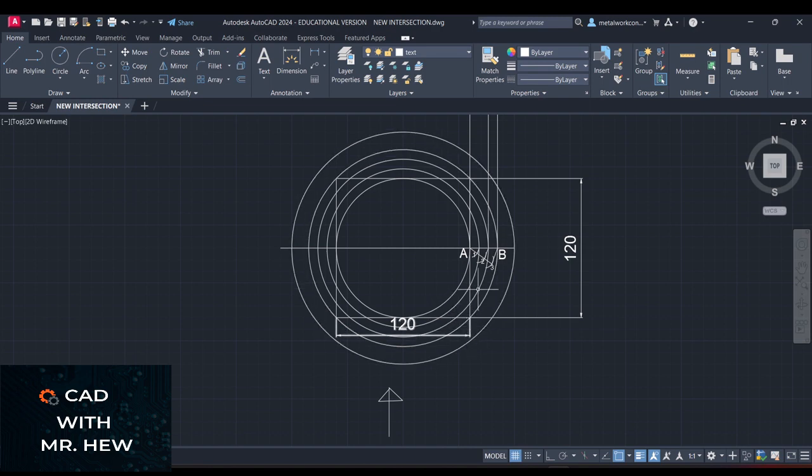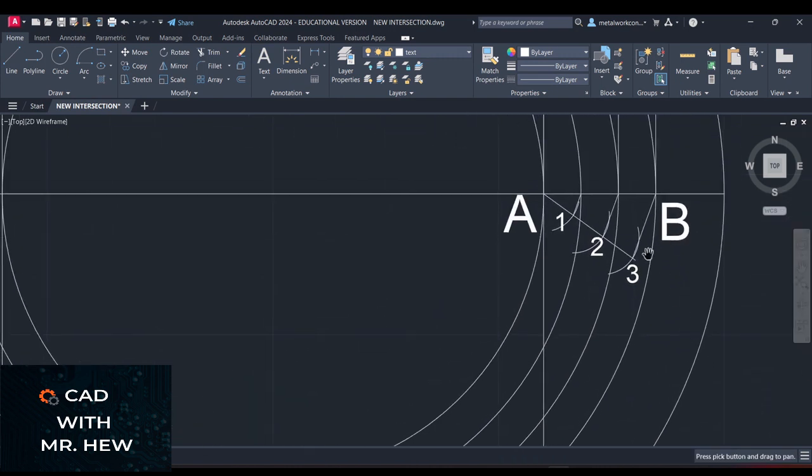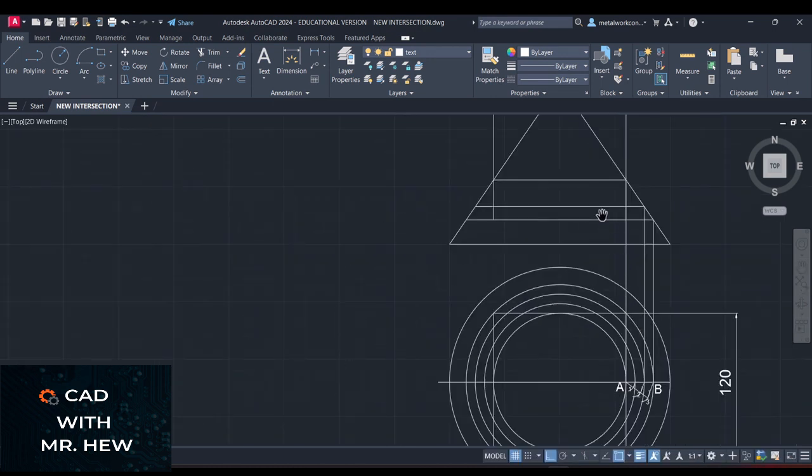All right, so we're going to plot it. Where the second disc, this one, intersects this line, you're going to project a line going up. So we go here at the intersection, which is right here. Can you see? Good. We're going to draw a vertical construction line to intersect the disc in the front elevation. Look now, its disc is here. Isn't that so? Yes, there. Enter.